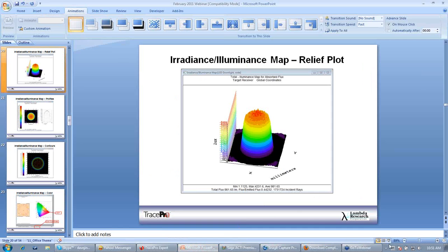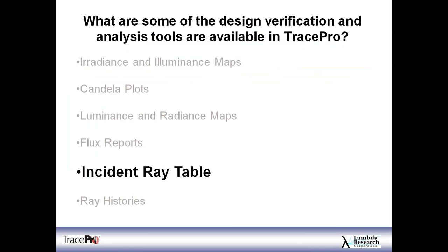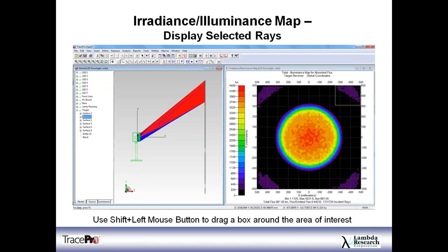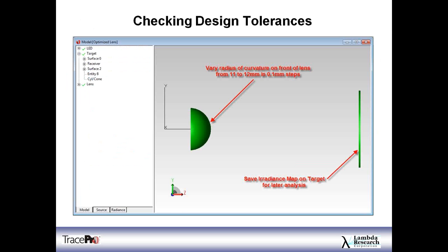Next question. Why do rays sometimes come out backwards from some of my LED sources when I build them and run the traces? And can I use reverse rays to reverse those rays? What you're probably seeing coming out backwards could be dependent on any surfaces or Fresnel reflections from surfaces. I really would have to see an example to see what's happening specifically.